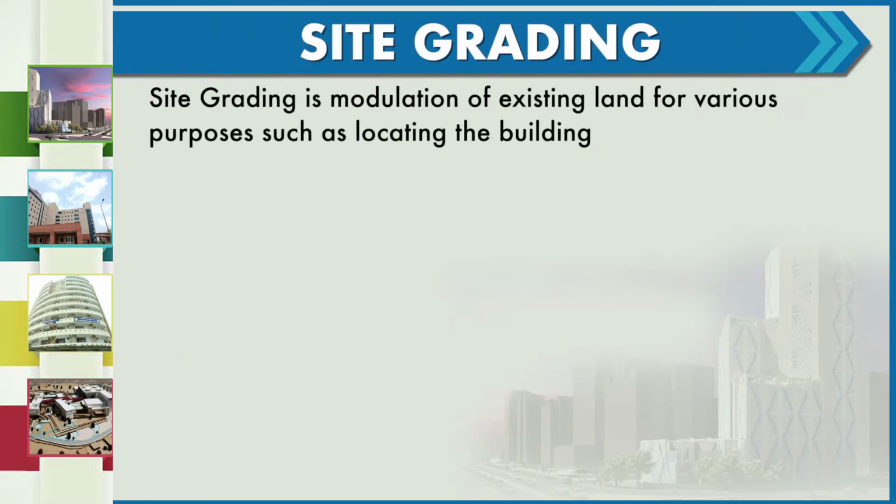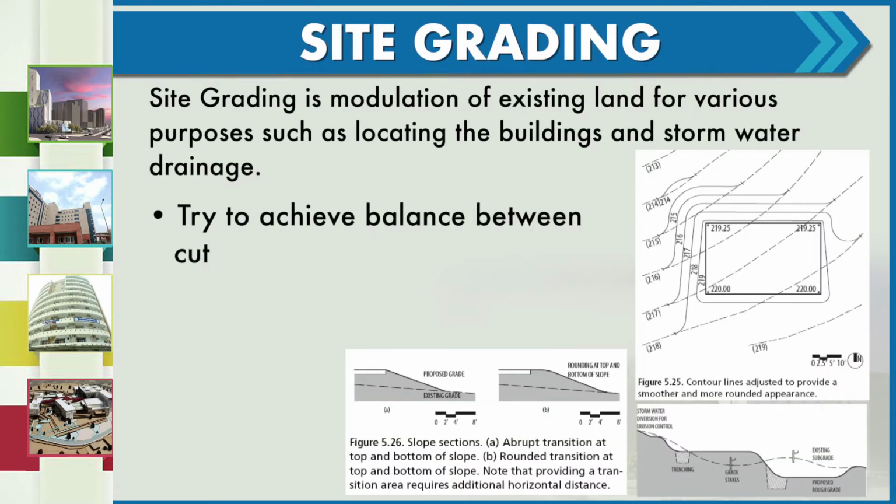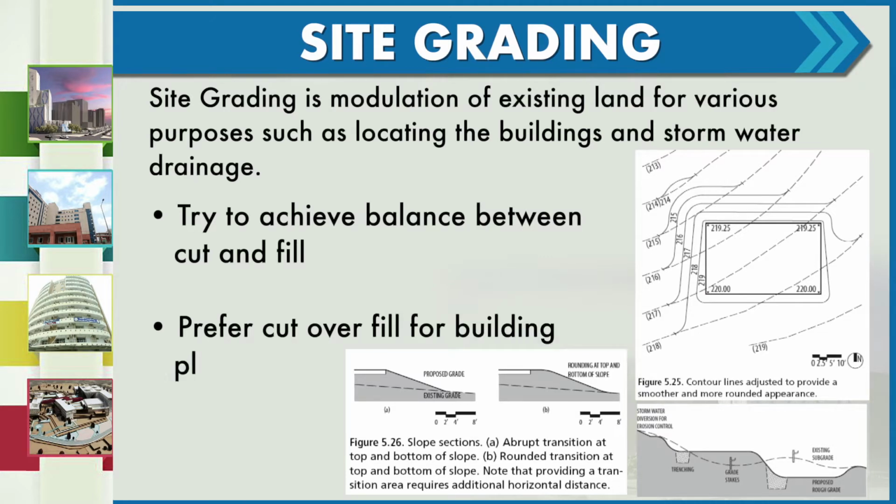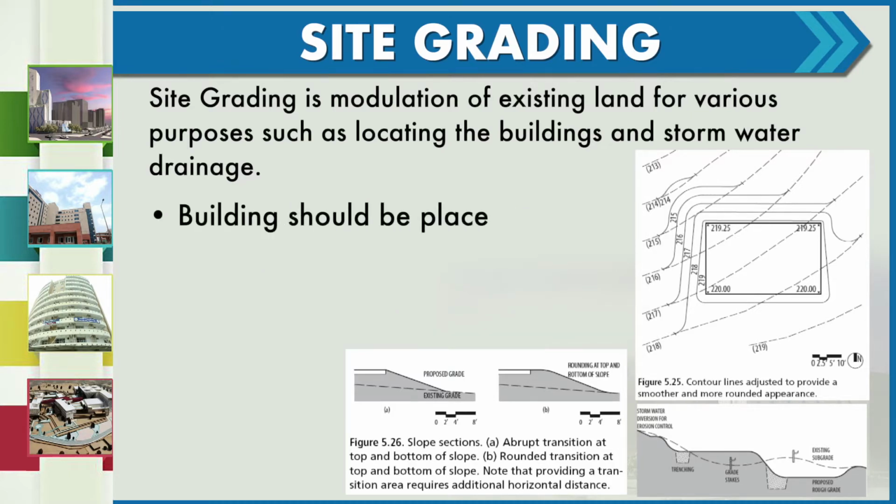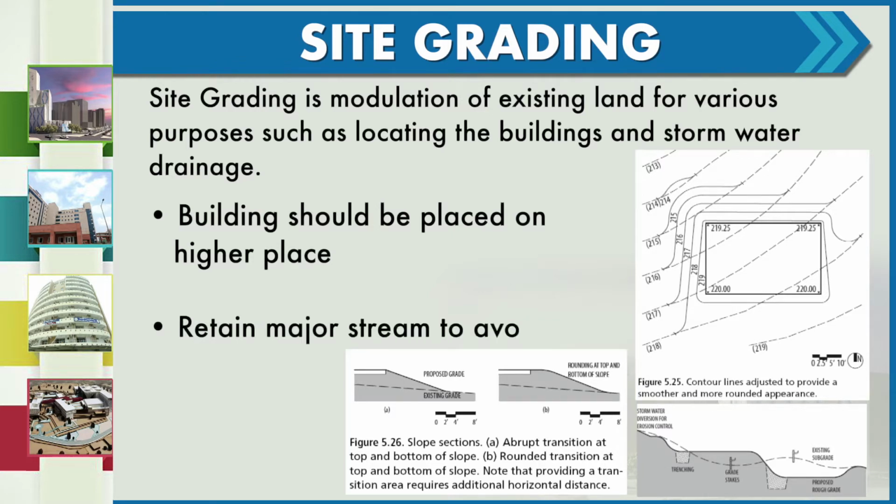Now we have to understand various points to consider while site grading. We should try to achieve balance between cut and fill. We should always prefer cut over fill for the building placement. Buildings should be placed on the higher places. Retain major streams to avoid waterlogging.